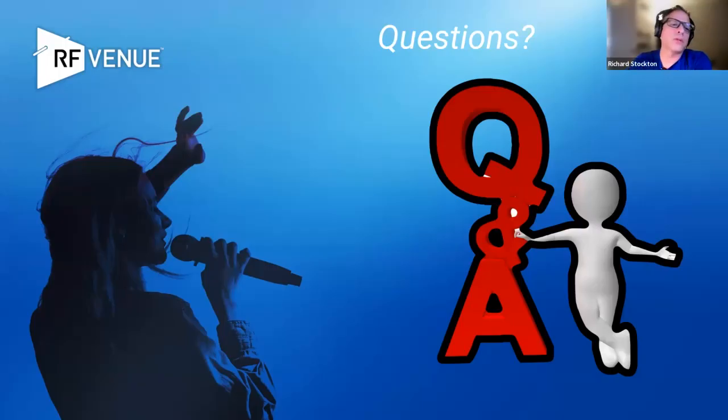I have something to add too. In regular wired audio, you have balanced cables. You should compare double shielded RF cables to balanced cable, even though it's not the same circuit. It's the bare minimum you should go for. You wouldn't run a microphone on an unbalanced signal long anyway. So you have to get the right coax cable. Awesome. Yeah, great question. Thank you for that.